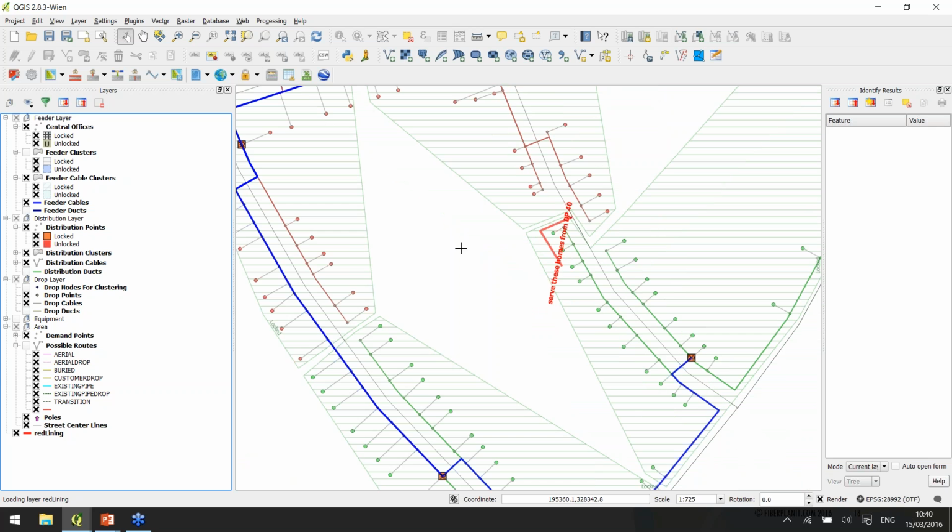So very easily, by just dragging and dropping, you can take into account these field survey changes. You don't have to change the cables, ducts, trenches themselves. Simply by changing the cluster, changing the polygons, you can recalculate your network, and the software will give you an updated network design and bill of material as well.